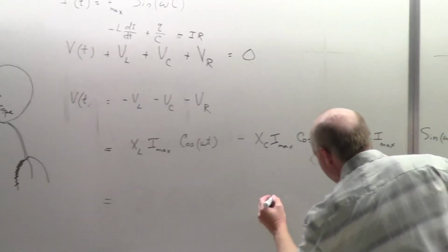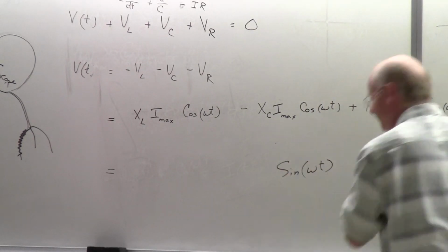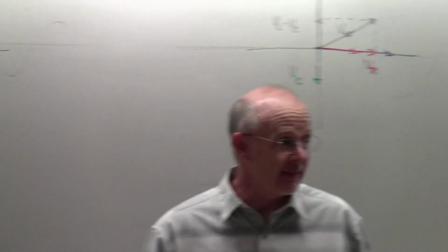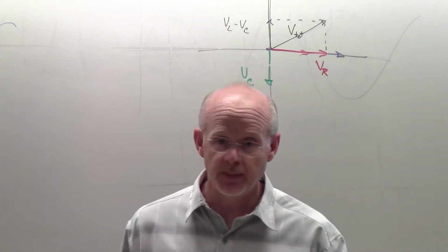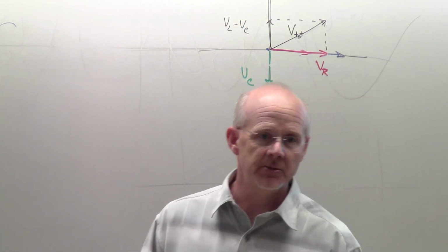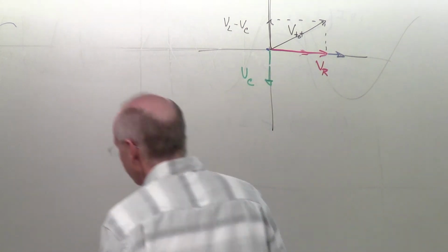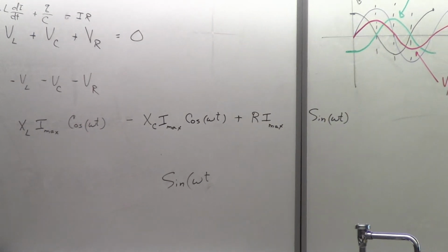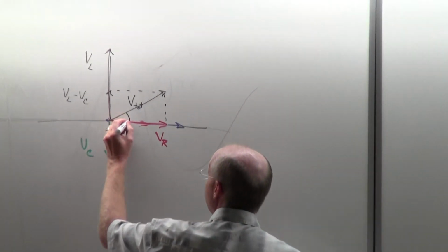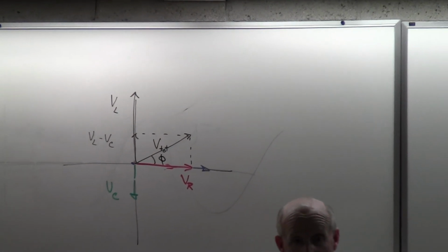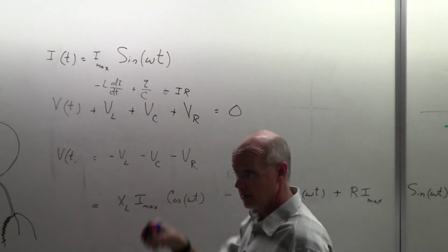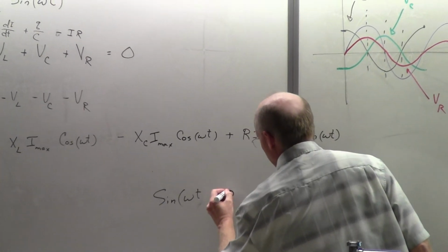All right, sine omega t. Yay! There's the first part of adding those three. That's the neat thing about the phasors. All of them spinning at the same speed are going to add up together to the resulting phasor spinning at the same speed. Sweet. Oh, I should have left this open a little bit. Because even you can see here, that stick that's spinning has a phase that is different than 0 from the current. So plus a phase.